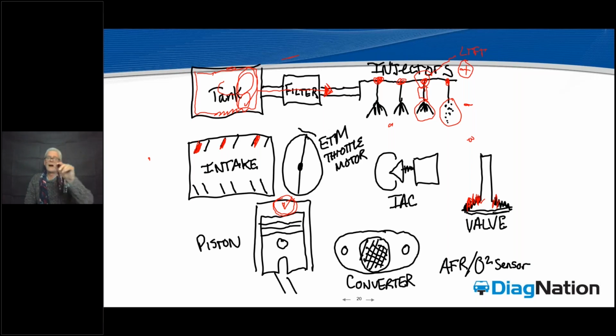And I've seen this so many times. That's why I say this is a tip or trick of the trade that you can take to the bank. If that thing's got a rough, raspy idle shake and it's a GDI car and it's got mileage, get into your baseline data, figure it out, because this is going to be creating it. Now, so we're restricting the intake.